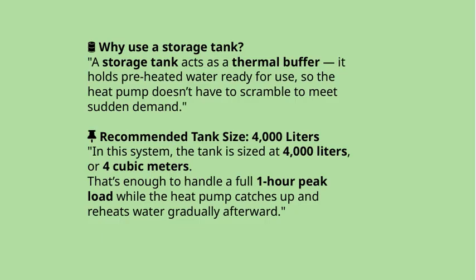Now, regarding the recommended tank size, we're talking about 4,000 liters. That's roughly 4 cubic meters of water. This size is ideal because it can handle a full hour of peak demand comfortably. While the system is working to catch up and reheat water gradually, this tank size ensures you won't run out of hot water during busy periods. Overall, using a properly sized storage tank helps optimize the performance of the heat pump system, maintaining efficiency and reliability. It's a key component in making sure your system runs smoothly and meets your hot water needs effectively.